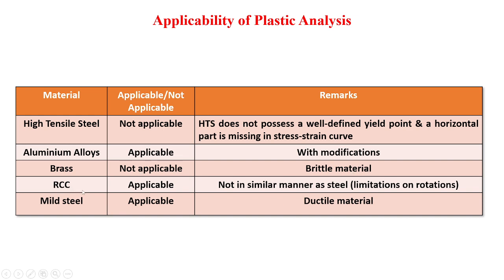RCC, that is reinforced cement concrete, is applicable. However, it is not applicable in a similar manner as it is to a ductile material like steel, because there are certain limitations on rotations. Whereas mild steel is straightaway applicable because it is a ductile material.